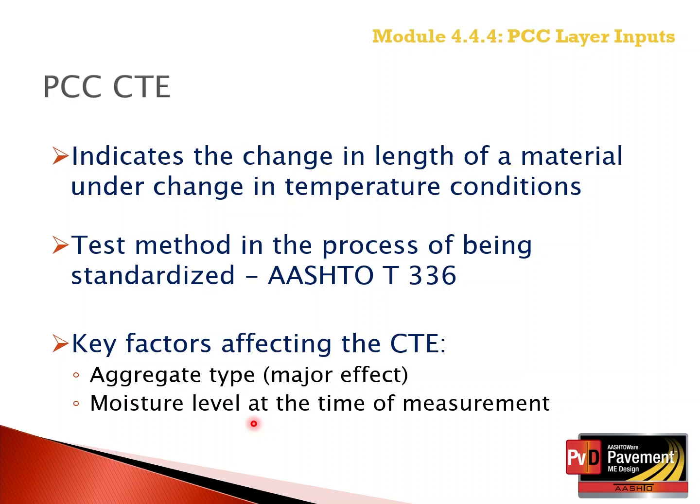Now, the coefficient of thermal expansion is measured in accordance with AASHTO T 336. The CTE, or coefficient of thermal expansion, defines the change in the length of the test specimen or PCC slab under a change in temperature. The CTE value has an important impact on the tensile stresses calculated at the top and bottom of the slab in terms of the curling of the PCC slab.